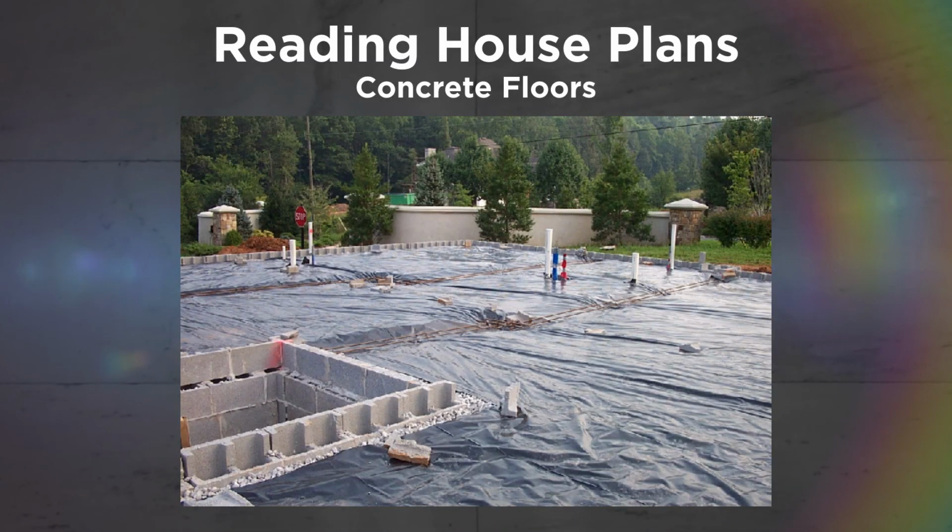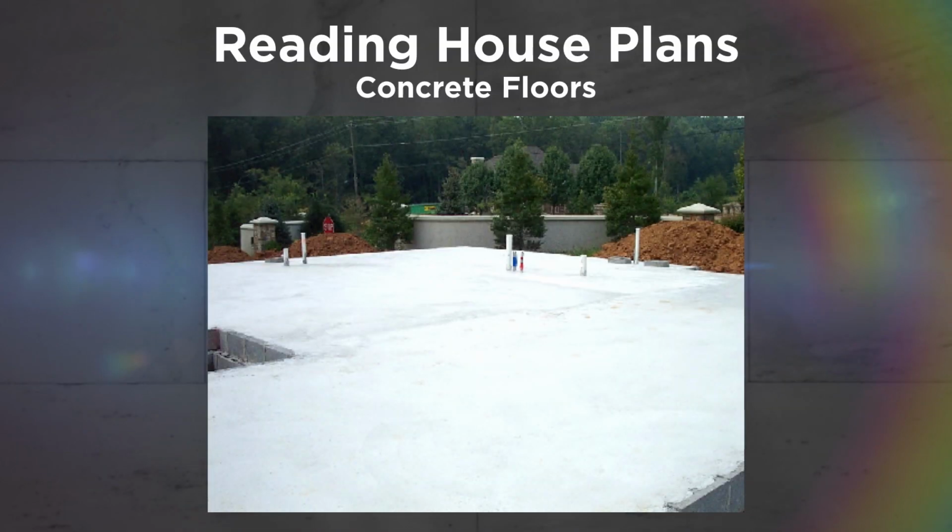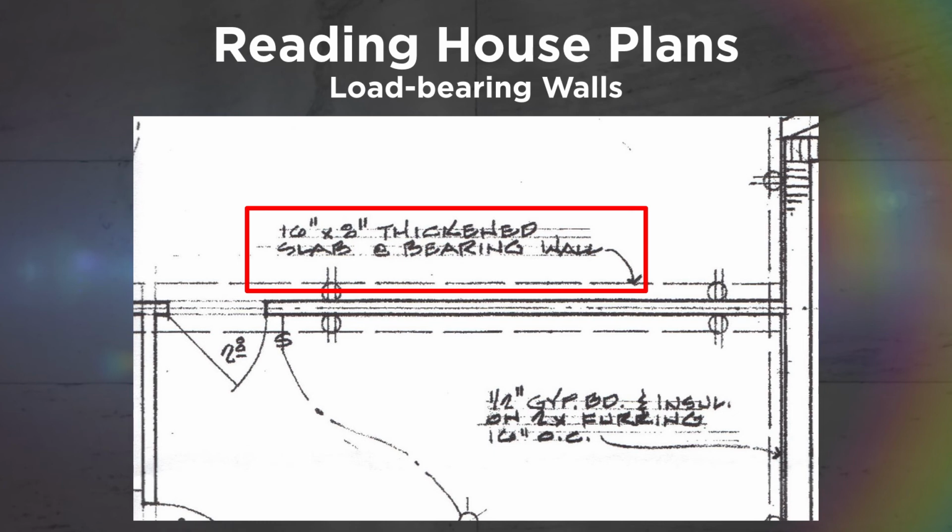Here is an example of the plastic moisture barrier covering the crushed rock. The plumbing has been roughed in according to the house plan, and the floor is now ready for concrete. Here's the same floor after the concrete was poured, and construction on this level is ready to begin. In a previous photo, you may have noticed that parts of the plastic were recessed in certain areas.